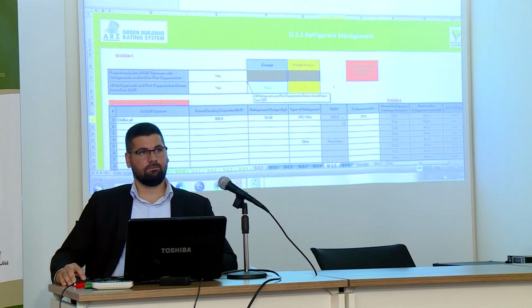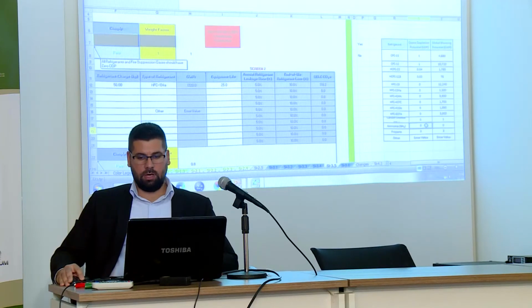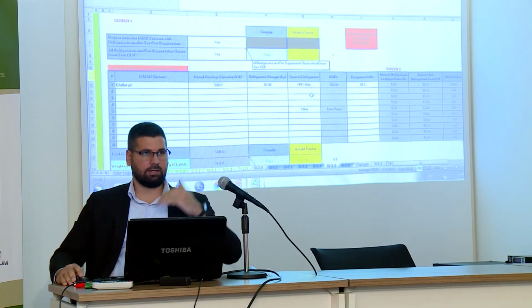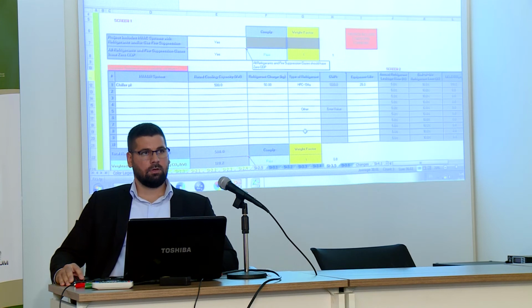So you said it has to have a GWP value of 0 to achieve 100%. That means if there is an air conditioning system, most probably it will never achieve it. Exactly. If there is no air conditioning system, it will get 100. I said if it has an air conditioning system, it will not be 100. Look, there are new technologies. You can see here that ammonia, for example, has a GWP of 0. Here the carbon dioxide also has a very low GWP, which is the reference for GWP measurements. There are also other new refrigerants that have very low GWP as well. So you can reach it, or at least you can reach the higher range of GWP. It will never be 100% unless it's a completely green gas.